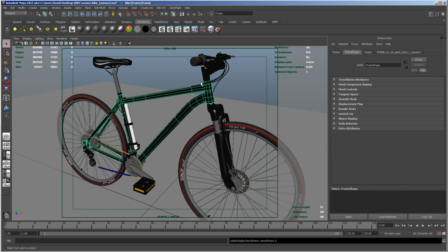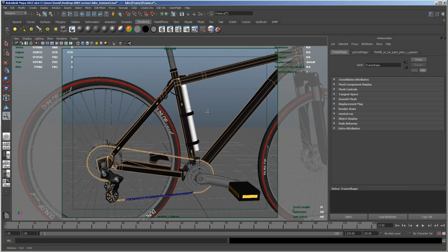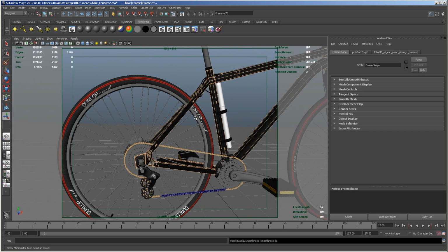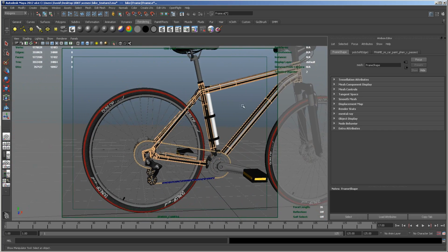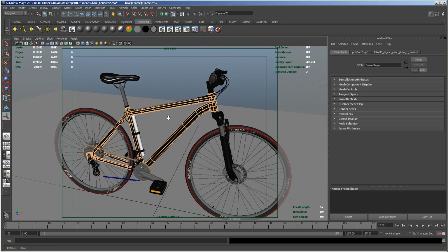It works in Mental Ray, so we can't use that. So what we use instead, I've hardened the edges again here, is in models we'll go to the normals and click soften, and that will soften them up, but it doesn't give you as good a result as using the soft number 3 key, the soft mode for Mental Ray. So that's why we were using it for this.